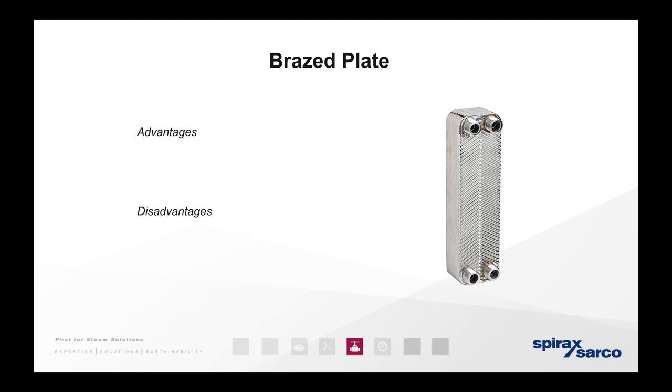Any other questions? Yeah, the same gentleman's asking, can you please define how pressure drops affect PHX and the optimal pressure range? So when you're talking about the flow through a heat exchanger, you need a pressure drop to have the flow of the steam, as in any steam line. The situation when you have stall is when your pressure drop actually gets closer to zero. So you end up with a back pressure, normally caused by a control valve before the heat exchanger that is closing.